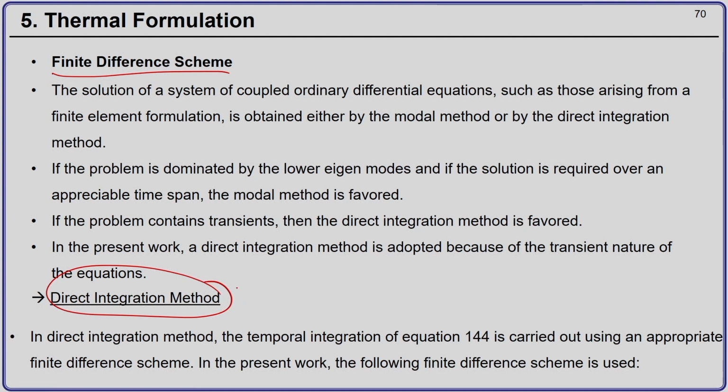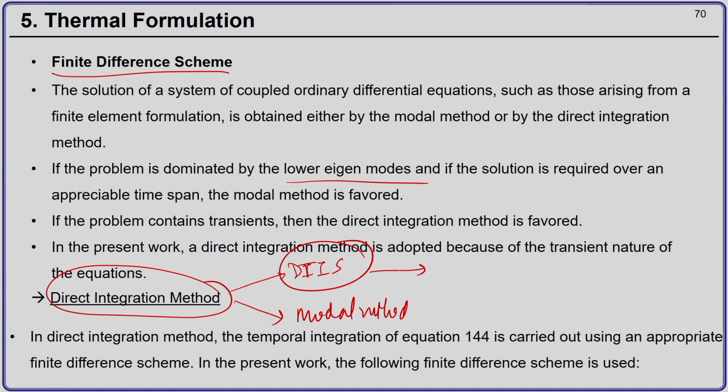Remember, time integration is of two types: direct time integration schemes and modal methods. Modal methods are usually favored when you have lower eigenmodes, and direct time integration works for all cases. So we use direct time integration, and for this we have to use an appropriate finite difference scheme.